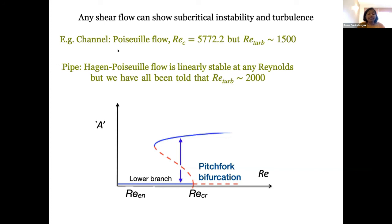Similarly, a pipe. This is called a Poiseuille flow and this is called a Hagen-Poiseuille flow. Both are parabolic profiles, but one is in an axisymmetric geometry, and that changes a lot. It changes a lot because if you write the Orr-Sommerfeld equation in an axisymmetric geometry, you'll never get any instability. The omega i will always be negative for any Reynolds number. So it's always linearly stable, unless there's some instability lurking somewhere that nobody has found till today. So it's basically linearly stable at any Reynolds number.